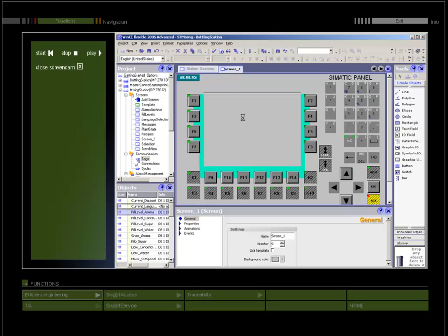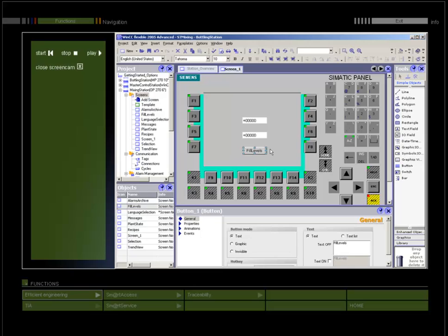You select the line or element you want and create the new objects using drag and drop. Example: generating an I/O field automatically by dragging and dropping a variable in the display, or simply selecting a display by dragging the object into the display image.